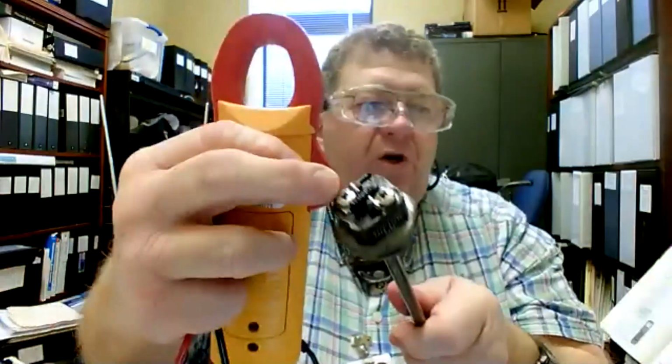When you do it, you want to make sure that you actually have the wires off of the screw terminals. So if this is actually in a water heater, you would want to make sure that you cut the breaker off, and then you come to this here and you check voltage. You measure voltage and make sure that there's no voltage there.